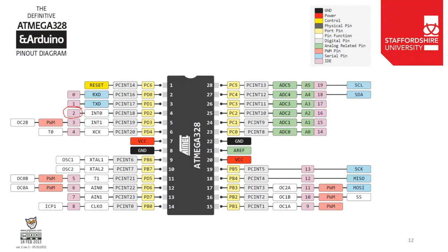So port D OR equals binary, and it's the second one, so it is the third bit, so it'd be 0, 0, 1, and we could leave it as that, or I could put in the leading zeros, or I could convert that to hex, and then port D OR equals 0x, not 0 binary.